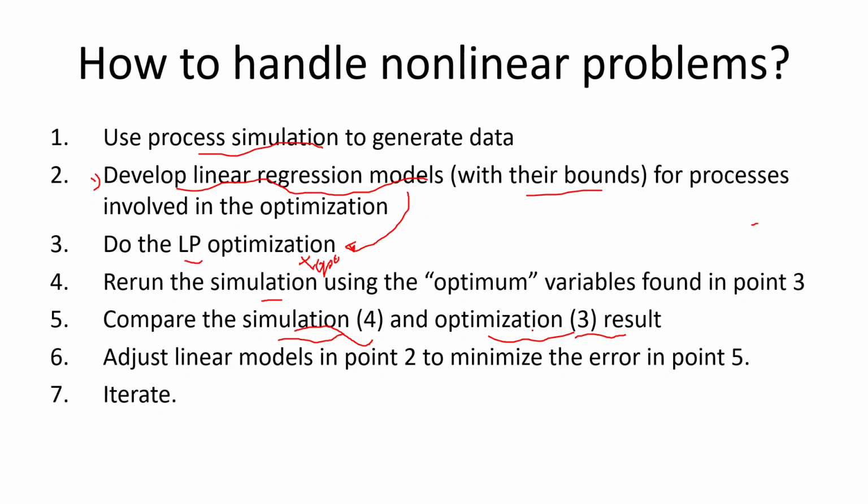And then you could also see the trend. If the trend is the same, it's just the order of magnitude. You cannot minimize anymore. So be it. What you need to know is whether you have to open that valve or close the valve, right? So then you can try to recommend that to the people on the field, and if they agree and it makes sense, then you can try it gradually, in a small change, and then basically you iterate.